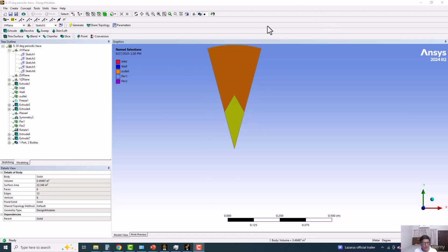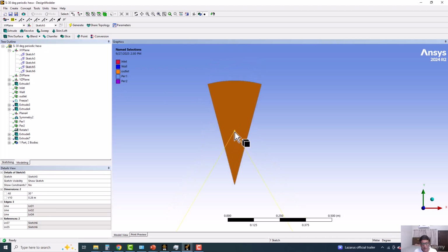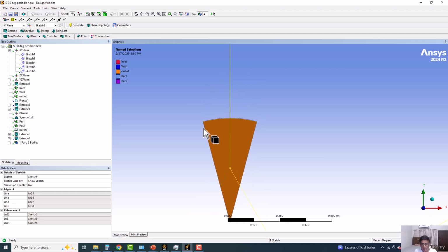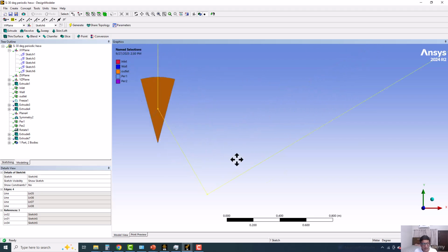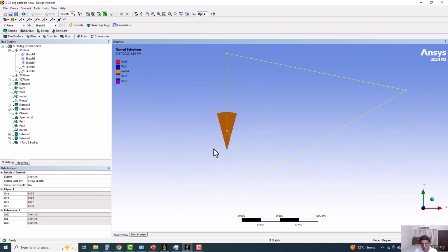Then I made another sketch, and that will take the first point from this point onwards. Then I made one vertical line, exactly vertical. It should pass through the center of your geometry. And then I made another line. This angle is not an important part. So I made another line going in this way. And then I made another line that was going through the same angle as the angle of sketch number 5. So on this side, same angle, and it should go outside.